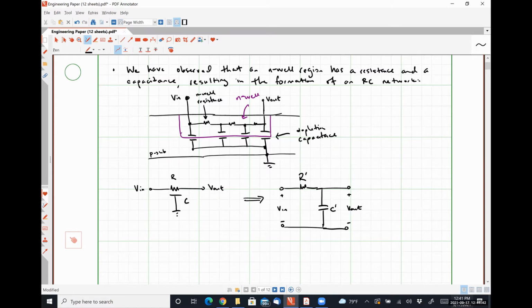So really all that means is that we're going to have resistance per unit something and capacitance per unit something. And because we're dealing with a planar system, those are going to be resistance per unit square and capacitance per unit square, or the sheet resistance we've been dealing with, and our unbiased junction capacitance CJ naught per unit area. Okay, so nothing particularly fancy there.